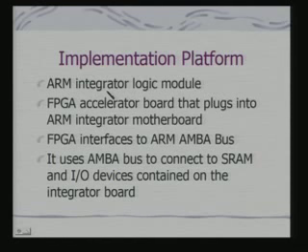Here you have a basic ARM processor based card, which may be an ARM9 based card if you are looking at the ARM9 integrator, to which an FPGA accelerator board can be plugged in. The FPGA interfaces to the ARM processor via the AMBA bus.